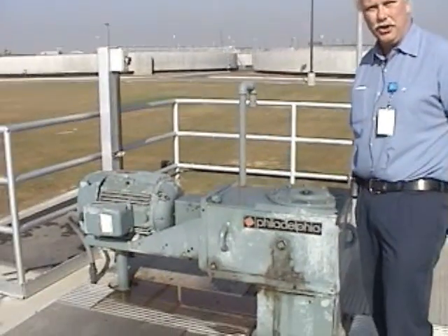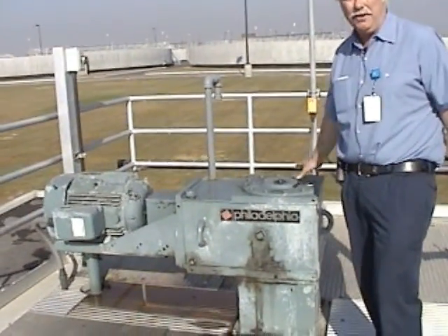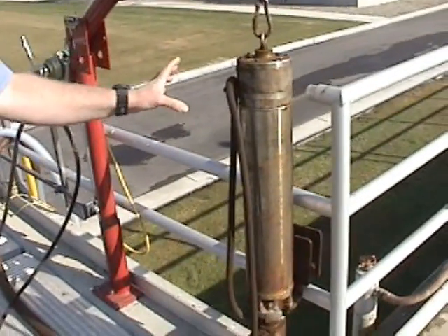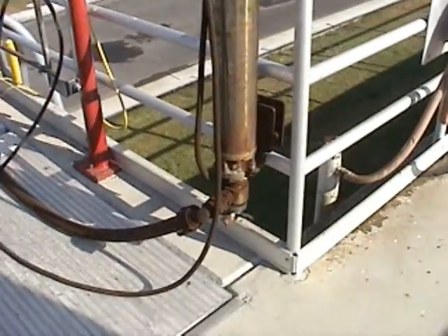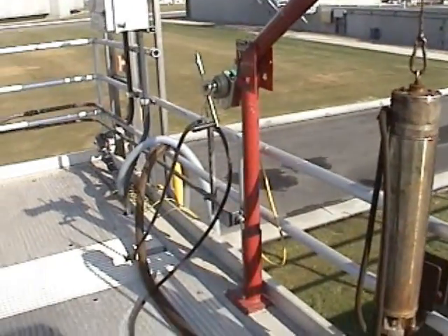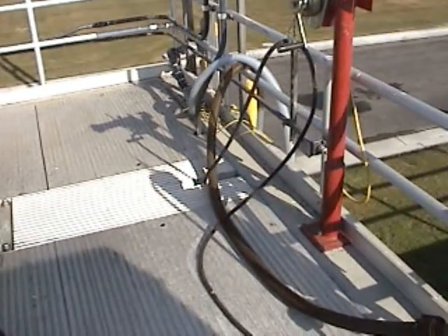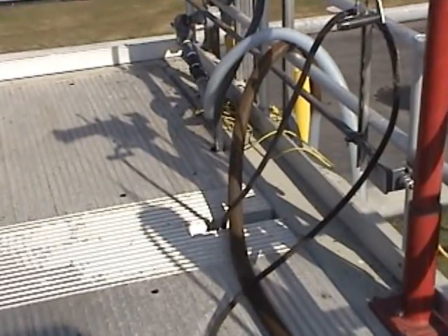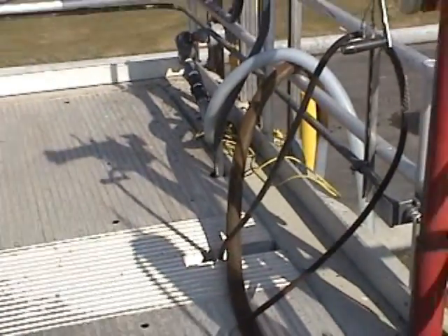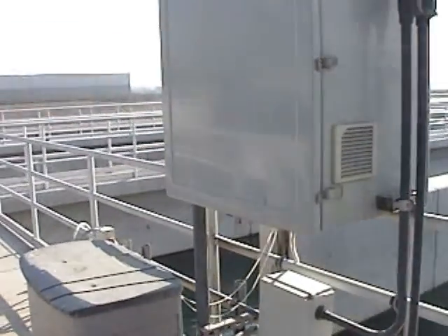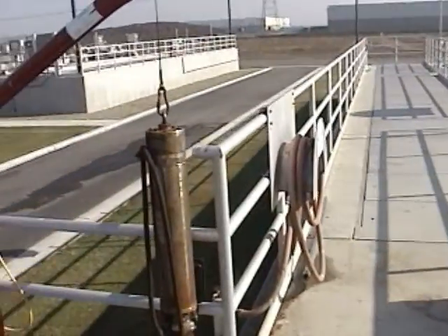The Philadelphia mixer is pretty obvious. If it's running, you're going to know it because you can hear it and feel it. The water champ, there's no indicators on this that it's not working. If it fails, what'll happen is you're going to have a high residual in one side of the tank and a low residual on the other side of the tank. Instrumentation will check it out and say, hey, the analyzers are right on. So what that tells me right away is the water champ has failed.